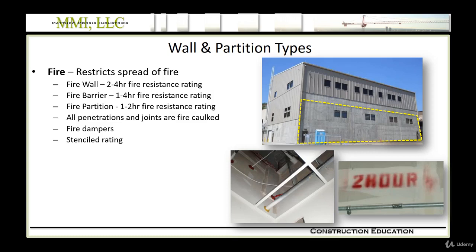And so you can do all that yourself, you can build your own assembly, but most often architects rely on established assemblies which have been deemed acceptable and published by the UL or listed specifically in the code. For example, if an architect determines that a partition needs to be a non-load bearing 1.5 hour rated assembly, there is an approved UL design for that assembly, complete with options for stud types, insulation options, gypsum board thicknesses, and number of layers. It even provides acceptable manufacturers and the specific manufacturer's product codes. So essentially, every time a design happens, the architect doesn't have to reinvent the wheel to determine their rated assembly.